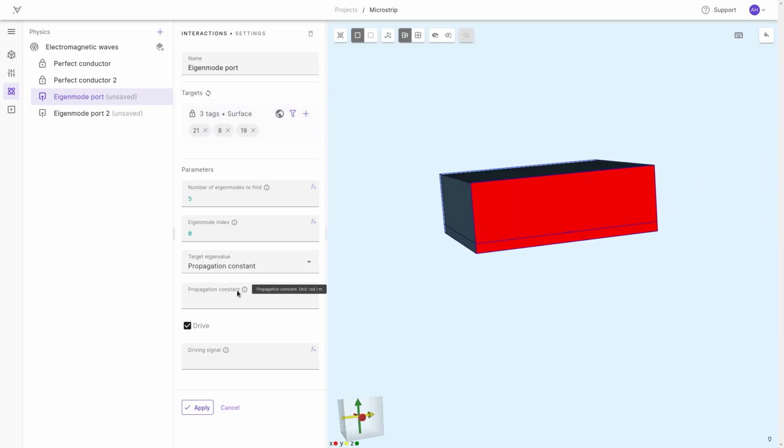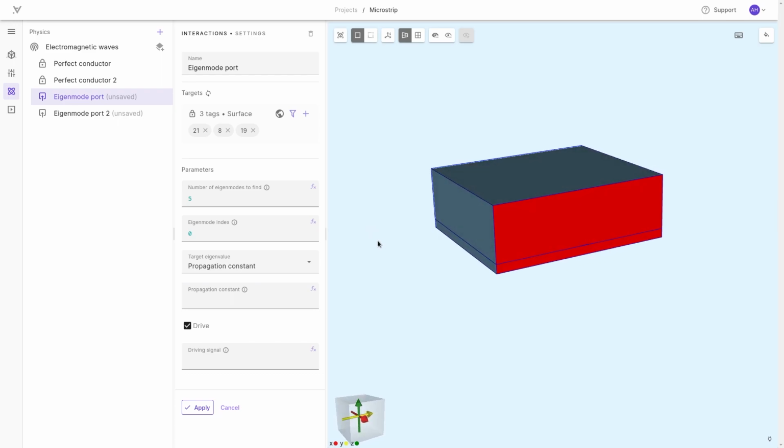Good. And then a few things. This is going to do an eigenmode analysis at the port. So it works for any type of ports, inhomogeneous ports, crystals, anisotropy, and lossy materials. If you have no idea of what modes can be fed and are propagating in this port, then you have to say how many modes the eigenmode solver should find. For example, 5 target. If there is only one like here, then it will just find 1, but the target is 5. After solving, as I will show in just a second, after doing an eigenmode port analysis, when you now know what can be fed through this port, you will have to pick out of the list of modes found. You have to pick which one you want to feed, in the order that has been found by the eigenmode solver.